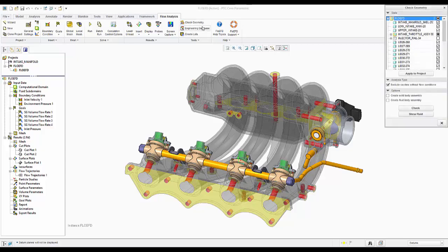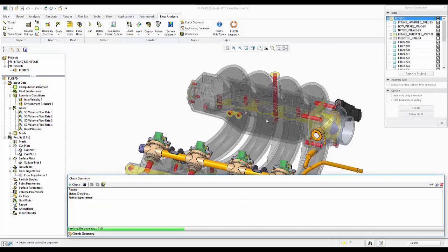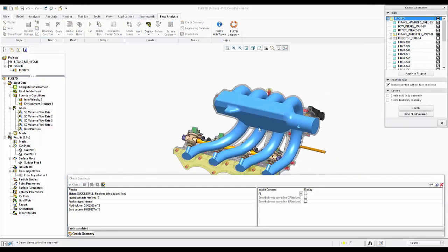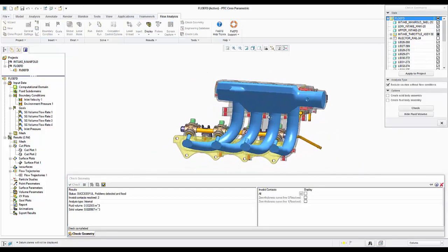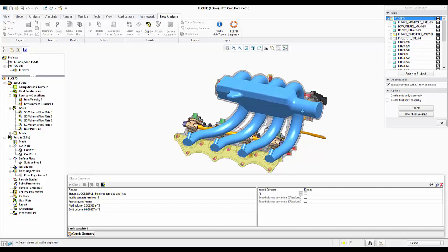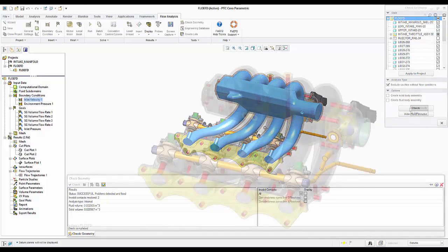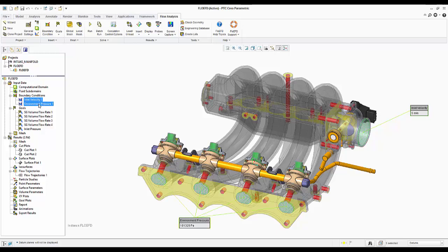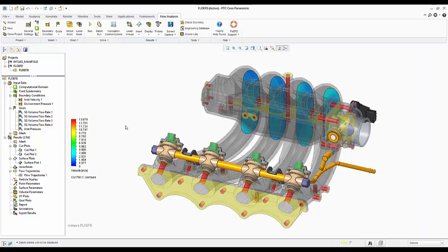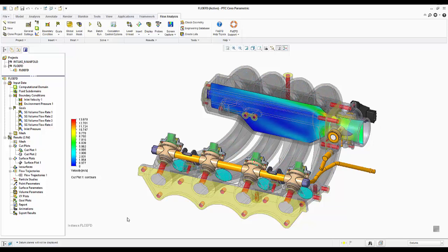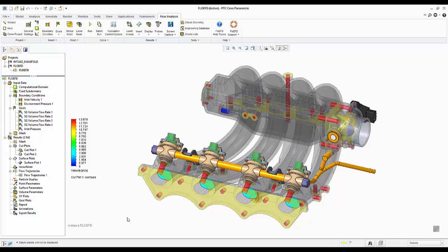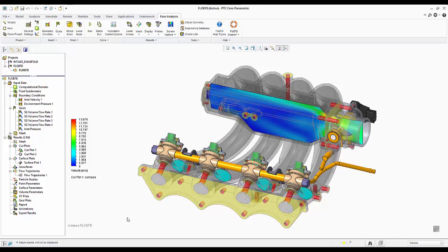Being Creo embedded has several advantages, such as being able to determine the fluid volume quickly and natively in Creo. Boundary conditions are also applied directly onto the Creo geometry by selecting faces in the view window. In this instance, we have an inlet velocity and 4 outlet pressure conditions. Post-processing is performed in the Creo visualizer also. For example, cut plots can be created and overlaid over the geometry and animated so they move through the assembly. This cut plot shows the velocity distribution slicing through the model.